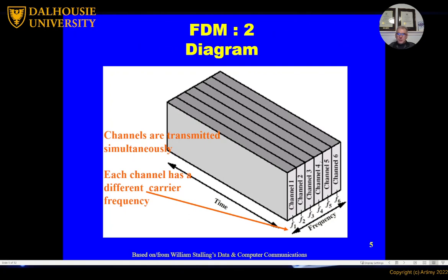So the first multiplexing technique splits the bandwidth. We have a large bandwidth available in the link. We chop that bandwidth into small pieces and we allocate each piece of bandwidth to a pair of communicating channels. So hypothetically, let's say here we have 6 channels, like the example that I gave earlier.